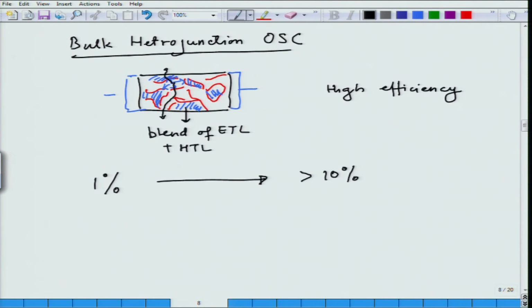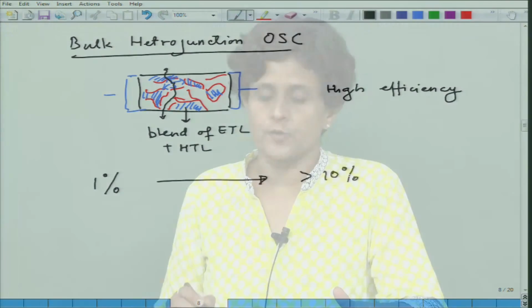So, you can imagine the kind of excitement, the kind of research and development that is going on in terms of finding materials which will give you better efficiency, because as we mentioned, there are different losses. First would be working on the device structure, so that reflectivity is less. Second would be working on materials which will absorb more. Third would be on the design side, such that the interfaces allow dissociation of excitons and then collection by the respective electrodes.